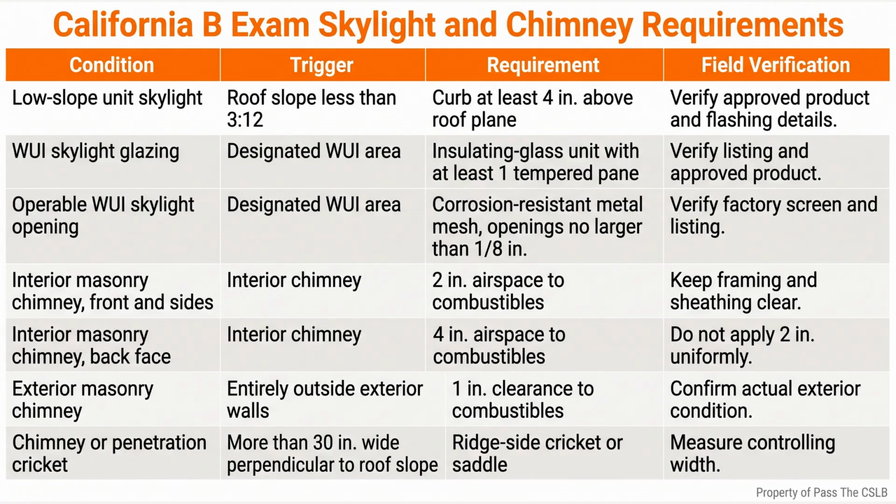The moment a roof opening exists, it is also a fall hazard. California Occupational Safety and Health Administration allows a temporary roof or skylight opening to be protected by standard railings and toe boards, or by a securely fastened structural cover. A cover must support the greater of 400 pounds or twice the weight of the employees, equipment, and materials imposed on any 1 square foot. Greater of means I calculate both conditions and use the larger one.